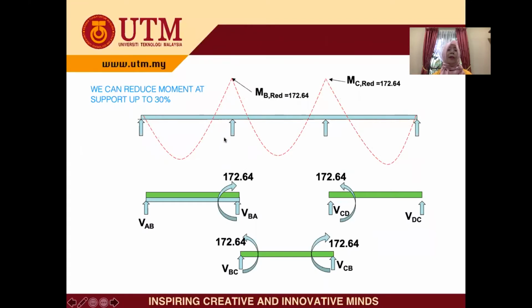Okay, for the case 1, now we have the maximum load. We force the support to have 172.64. Then we need to recalculate what is the VAB, VBA, VBC, VCB, VCD, and VDC. Do again with the similar procedure as above.